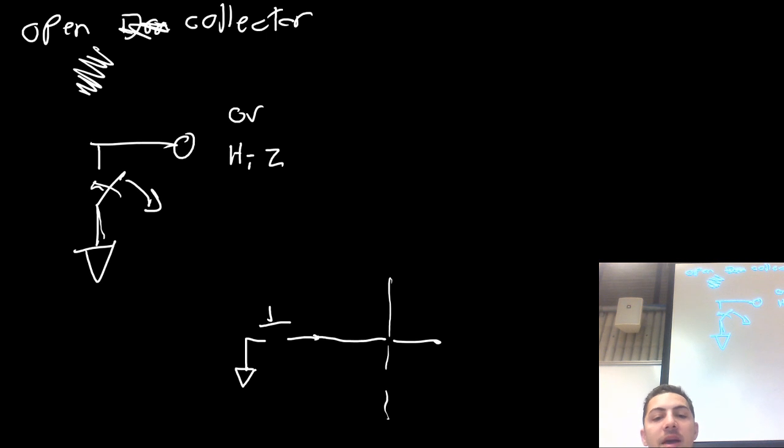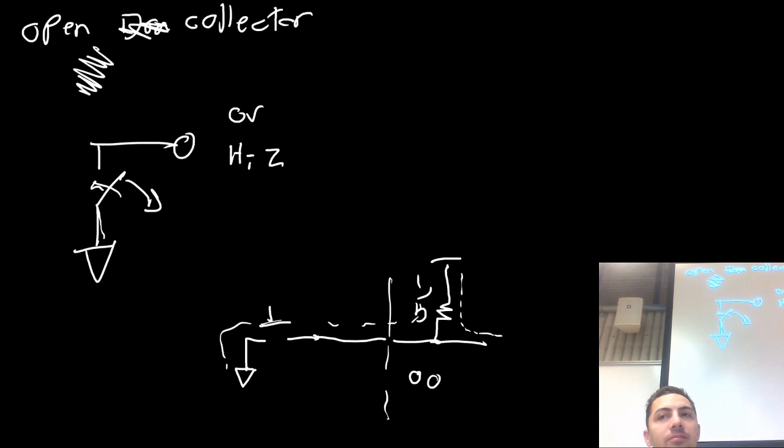We need to somehow make this show both 0 and 5 volts. Right now we can only make it show 0 volts. There you go. Say it loud so everybody can hear: a pull-up resistor. That internal pull-up resistor. So now when the button is not pressed, small current can flow that way. When the button is pressed, we're still at 0 volts and a little bit of current flows to ground.